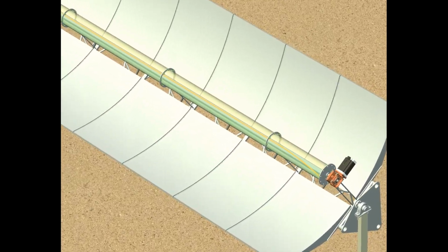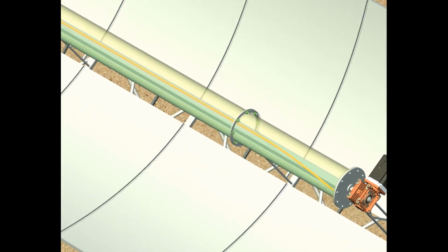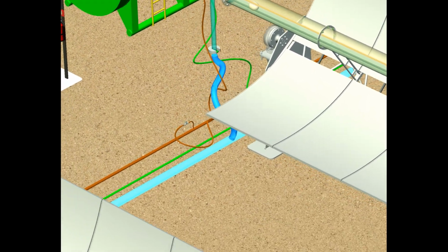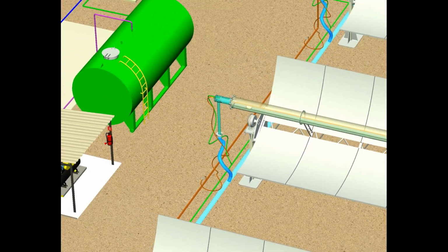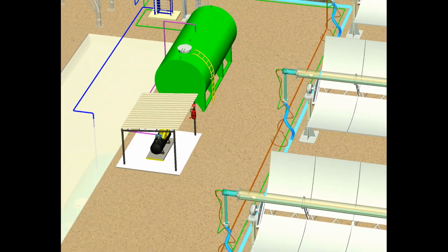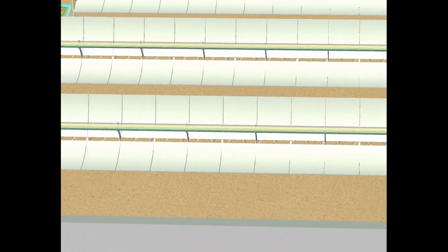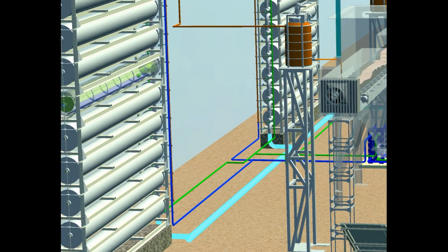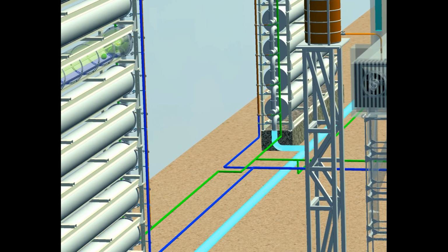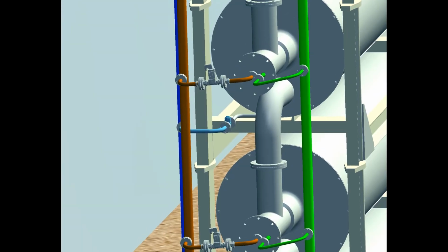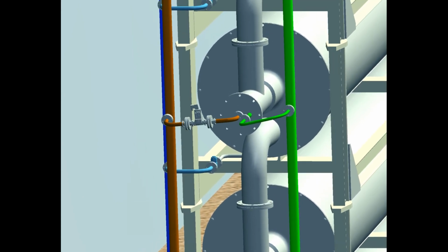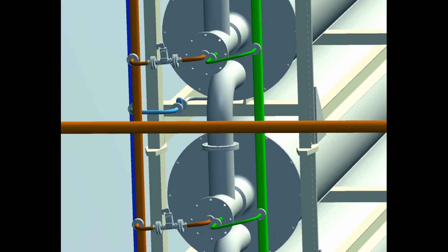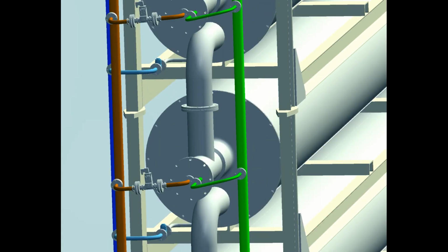In calculation estimates, it is accepted that the surface area for reflecting solar rays is 70 square meters, and to ensure the average productivity of a multi-stage desalination plant of 22 cubic meters of fresh water per day, thermal energy is required from 3 reflectors, which can provide the required amount of high-parameter steam. In the presence of high-pressure steam of 550 kilopascals, which is generated in film evaporation drums installed in parabolic solar concentrators, it is possible to ensure a multi-stage evaporation process according to a sequential installation scheme of film evaporation drums. In this case, for the design under consideration, the solar desalination productivity can be increased by 10 times.